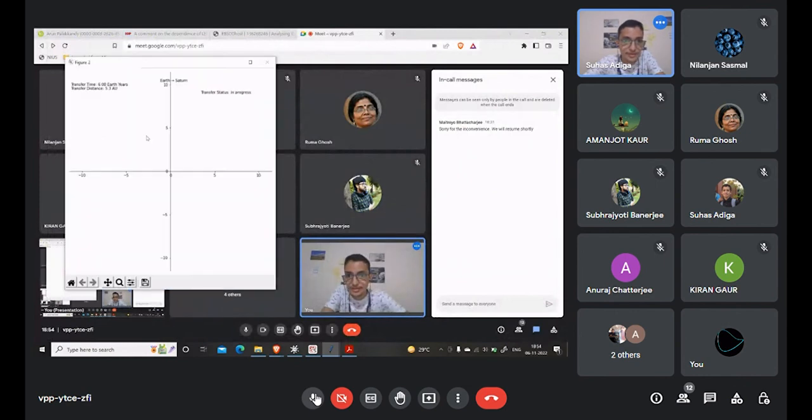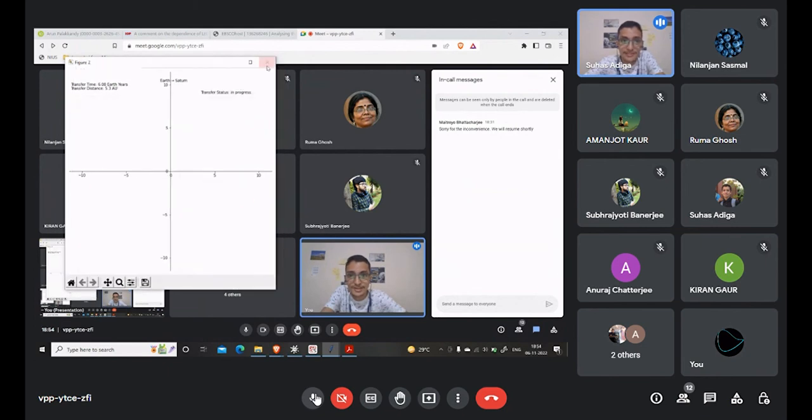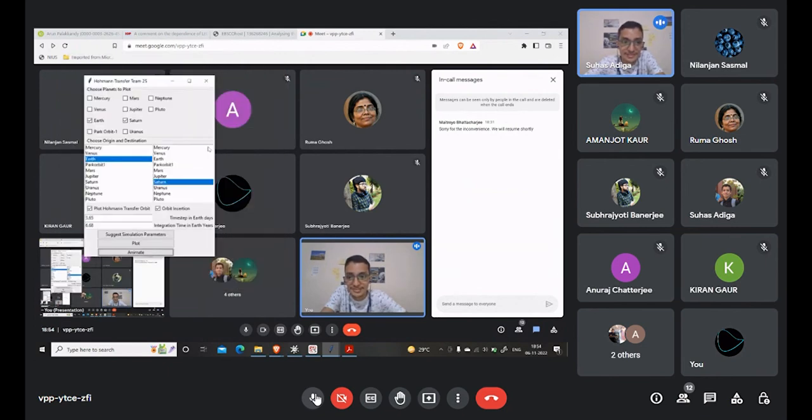So now you can see it will be a bit quick. But again, you can clearly see that this will not meet, or usually for the planets which are there in the last, that is, I said the cases where bi-elliptical is more favorable. Those cases you can clearly see that it does not meet. So you can clearly now see that there is a bit of a difference. This is mainly arising due to the computational errors that we are having in the approximation in this leapfrog method.